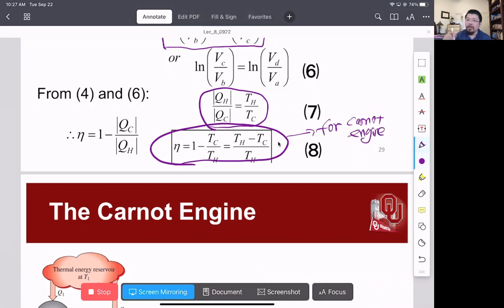Whether it's the standard Carnot heat engine or the reversible Carnot engine, or the refrigerating process, we are using this as the efficiency calculation. So if you think about 1 minus TC over TH, and what we just talked about, TC is roughly around 300 Kelvin, very convenient for liquid water. TH is roughly 500 to 600 Kelvin, and that is the limitation we have to accept. Using steam, using liquid water, the best engine efficiency is around 30 to 50 percent.